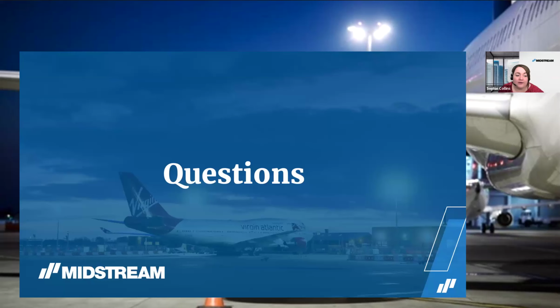So I think along the same lines, how do you evaluate 3 stands that are next to each other? Do you evaluate each apart or all together? They always have to be evaluated singularly, because you have to think that is what you're operating, that aircraft stand. Then there is a value which actually comes from a different part of the normative, which is other apron areas. So basically a rule is that neighboring stands, like any neighboring areas, cannot be less than 50% of the one you're evaluating.